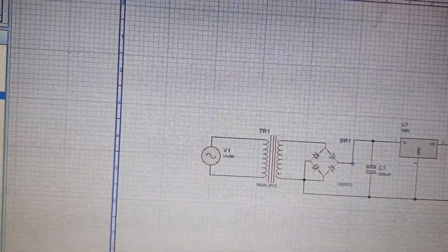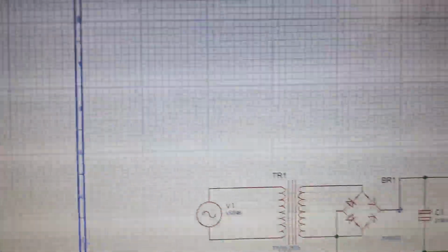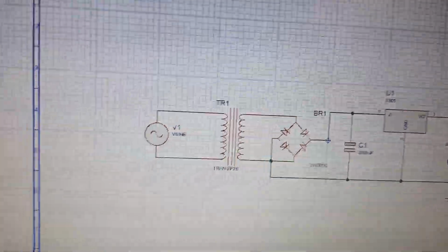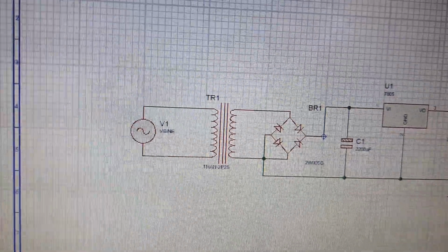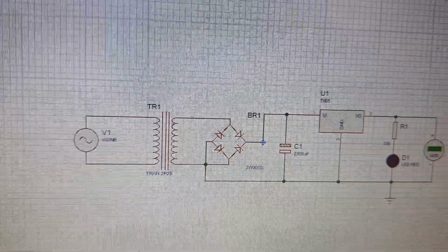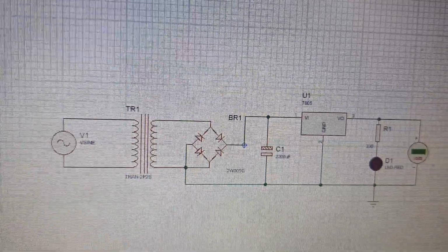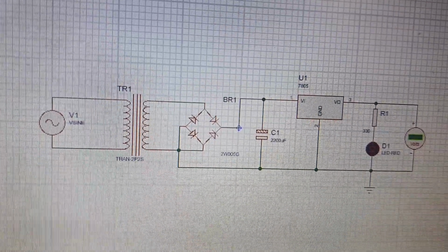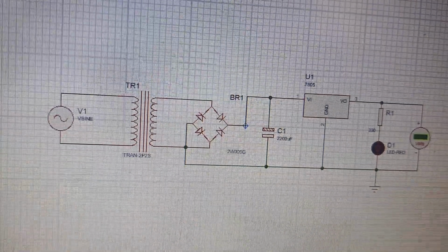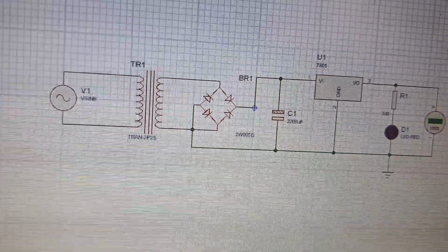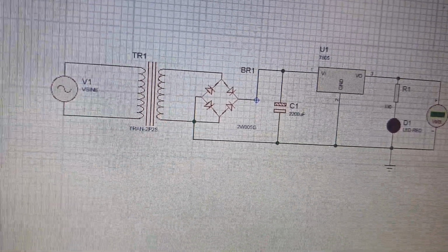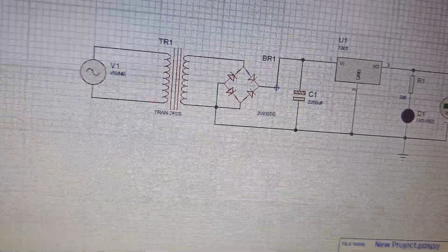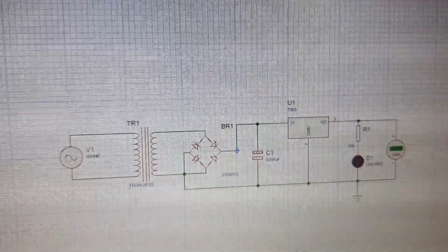Now, if you closely observe the figure, then you will notice the capacitors connected across the 12 volt are of high voltage rating, while the capacitors connected across the LED are of low rating. The purpose of applying capacitors is to remove noise from our DC voltages. As we know, the DC voltage source available in the market is not that pure. So to get a pure DC wave, capacitors are connected to it.